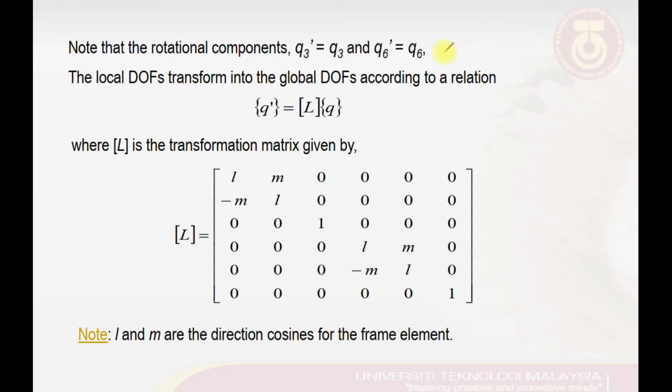However, as I mentioned just now, since we are first working in the local coordinate system, later we have to transform all the displacement and rotations, or the deformation which we derive or work in the local coordinate system, and transfer it into the global coordinate system by applying these transformation matrix.